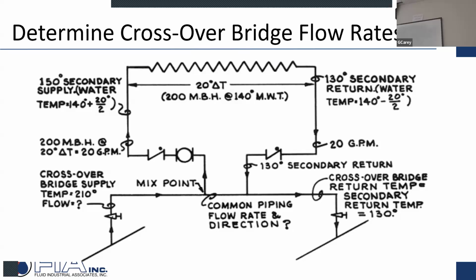Well, this is going to be 20 gallons a minute. So I've got to figure out, I've got this pump back here that I can't see in this drawing that's feeding all of these crossovers. And this is one of them. So I've got a balance valve so I can balance it, and I make sure I have the right flow rate coming across here.